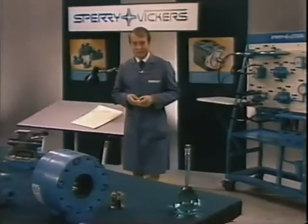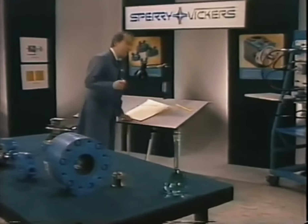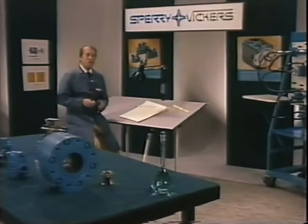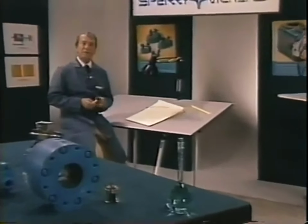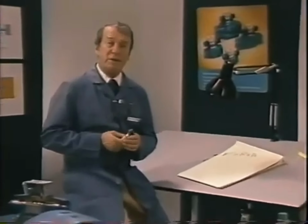Back at the start of this discussion, we used an electric motor to drive a pump, and you may have wondered, how big a motor? To determine this, we have to know how much force or torque was needed to do the job. That would tell us the pressure required and the size of the actuator. Then, knowing how fast the actuator had to move, we could determine the amount of fluid in gallons per minute that would be needed. Well, we have a formula to determine the horsepower required to move a given flow rate at a known pressure. You may want to make a note of it.